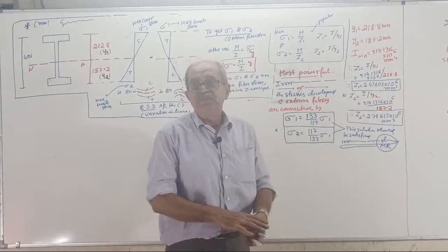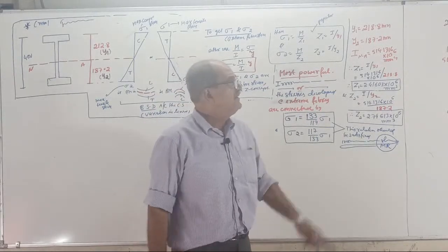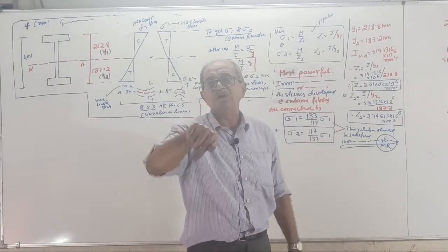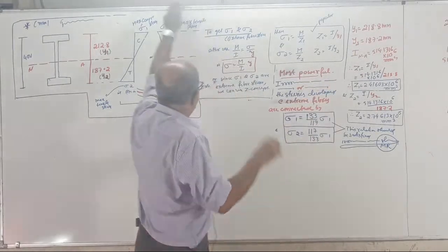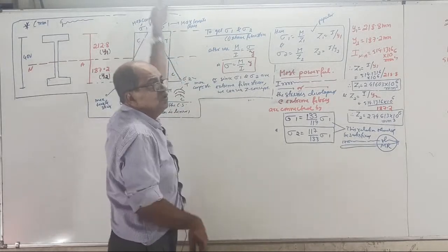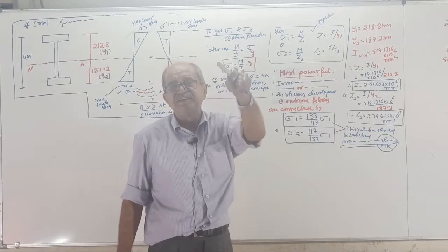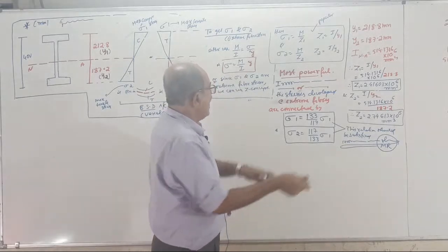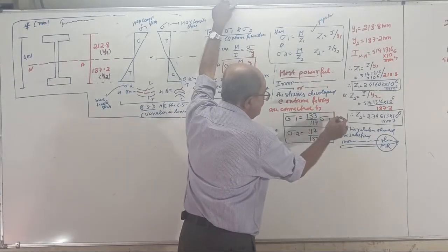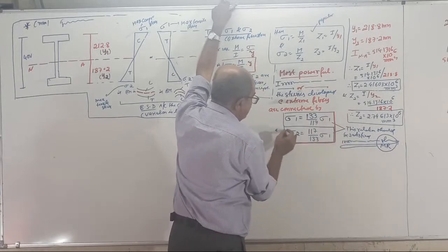Or, if you are a safe person, better check how much money you have got before eating. That is, before applying bending moment, you check how much maximum BM the cross section can resist. That is called MR. Whatever you do, this is to be strictly satisfied.